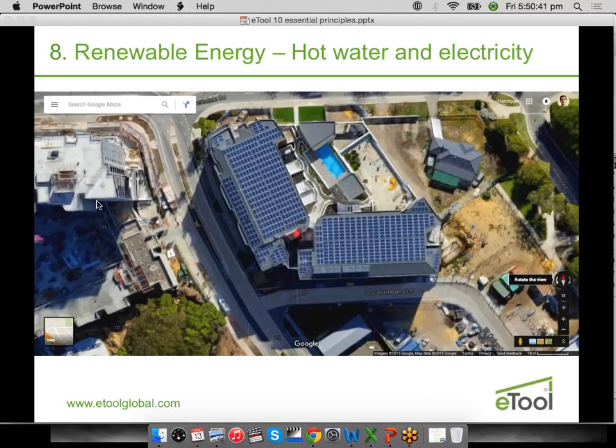And this is the aerial view of this development, the Psaros building. This is interesting because this is north here. So all the services that they had, this, I don't know what this is, the lift, it was all designed so it was maximizing the availability for solar contribution. So they're minimizing shading, they're minimizing protrusions and gable roofs. They're just trying to design the roof really flat so you can install as much as you can. You maximize the generation capacity.